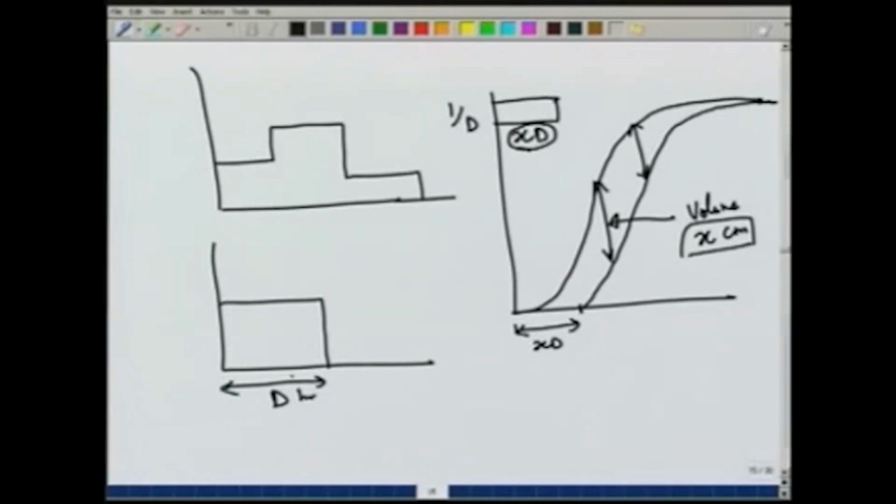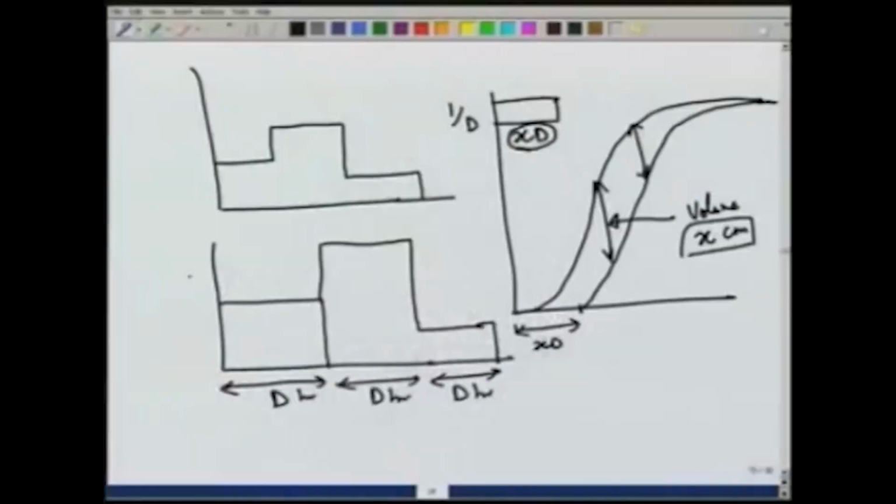rainfall. In some cases, it is not possible to get these very ideal kind of storms, and sometimes it may happen that we have a rain occurring over d hour periods, but with varying intensities. So, if we have the runoff corresponding to these complex storms, we can still derive the unit hydrograph, but then the computations become a little bit complicated.